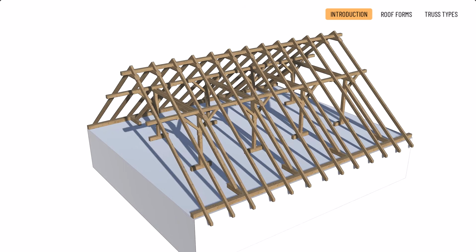Pitched roofs are traditionally, even today, mostly wooden truss structures, which can be built in a wide variety of shapes and at different pitches. Both the form and pitch of a roof serve functional and aesthetic purposes. The primary goal of roofs is obviously to meet basic performance requirements dictated by climate, to protect the building from weather conditions such as precipitation, wind, cold and heat, while separating the interior spaces for storage, living and other functions, similar to walls. The roof truss serves as the load-bearing structural part of the pitched roof, bearing the weight of the roof and transferring it to the structures below.